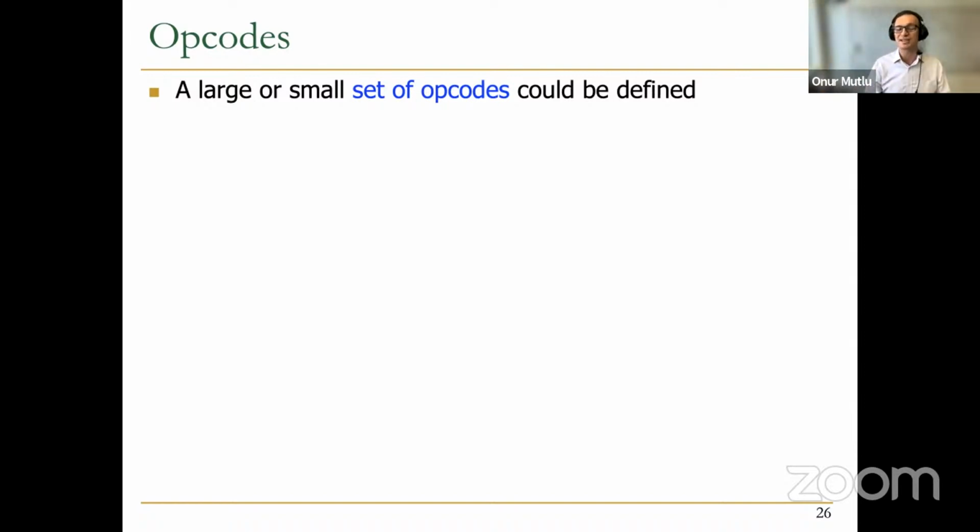Now you can imagine that there's a huge trade-off space over here. Does it really make sense to have a matrix multiplication as an opcode in your system? How often does your system execute matrix multiplications, for example? That could be one consideration. So basically, there's no end to this, if you will. You can specify a doubly linked list insert operation as an opcode potentially, right? So it's based on the imagination of the person who is designing the interface, and also what happens in the software, right? Ideally, you would like to map the software constructs nicely to the opcodes.